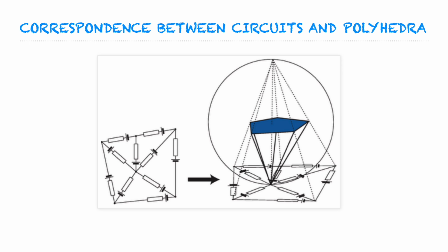Any convex polyhedron surface has Euler characteristic chi equals V plus F minus E equals 2. Now it is evident that the number of vertices of the polyhedron corresponds to the number of nodes of the circuit, and the number of edges corresponds to the number of branches of the circuit. However, the number of faces F of the polyhedron is equal to the number of elementary loops plus 1 in the circuit, because the topmost face represents the open area surrounding the circuit.